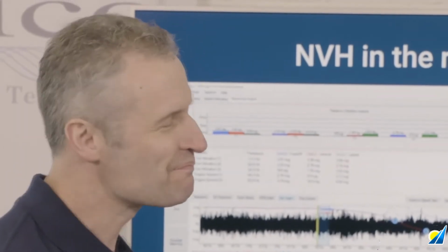Well, the other message here is, look, this is a fairly simple engine. We can actually visualize and see all of the components very easily. What if this was a V10 Audi, where it's 20 hours to get the engine out of the frame, just on the suspicion that you might have a front end pulley noise? We can't make those decisions. We have to have hard evidence. And the NVH has provided that evidence for us.